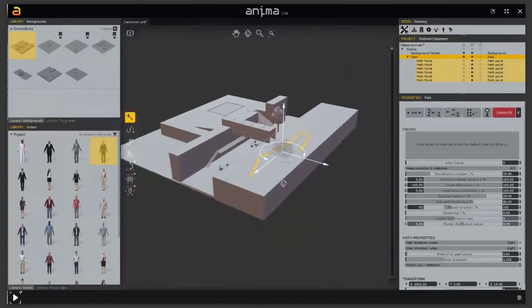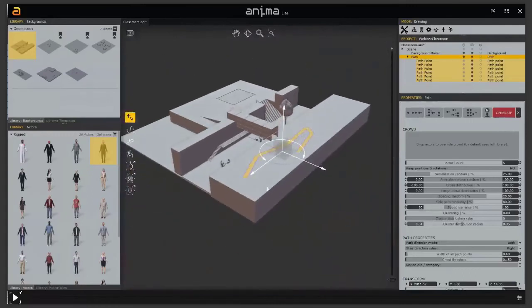This is due to precision, in this case, in the render of these elements. Now, one important thing is that precision is not just about drawing these elements. Precision, in this case, affects the collision generation, and since all the simulation elements are strictly related to the collisions, the worse the collisions are generated, the worse the simulations will be.